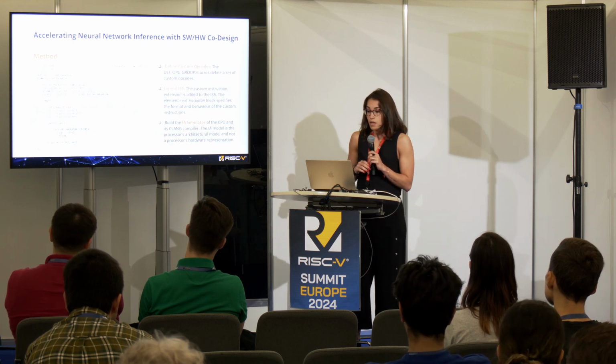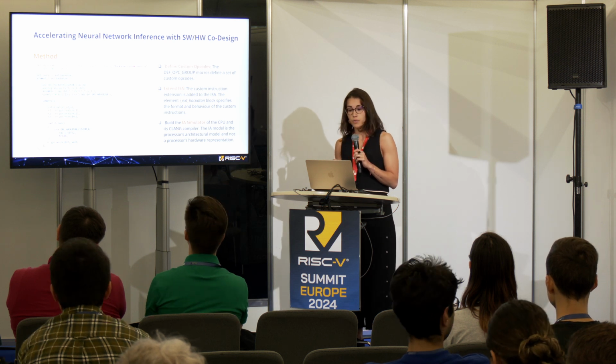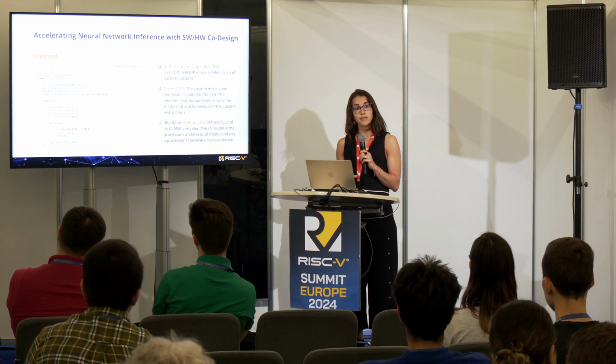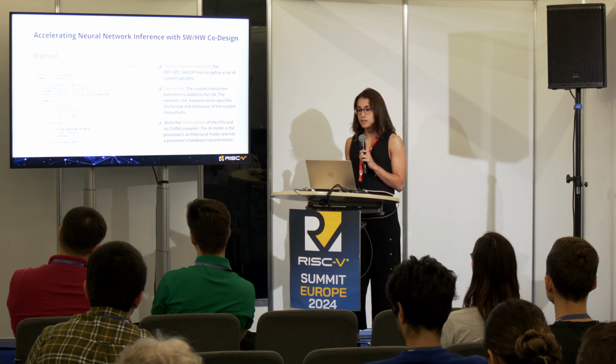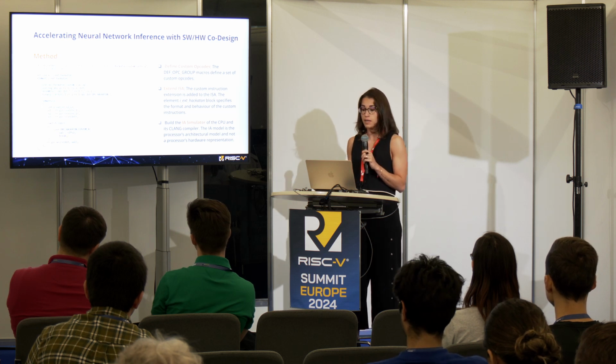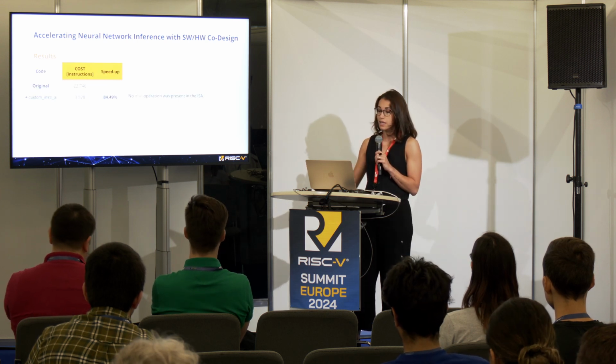22,646. So the method consists in defining with macros the different opcodes for the new instructions and adding the different instructions to the complete instruction set architecture of the core, and recompiling each time a new instruction is added the ISS simulation, which is an architectural model and not an RTL model, because of course in 4 hours we don't have the time to simulate all the RTL.